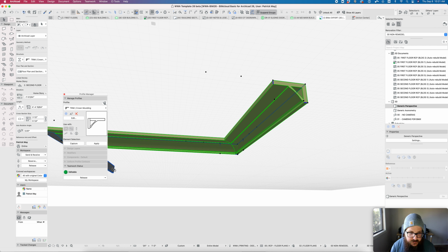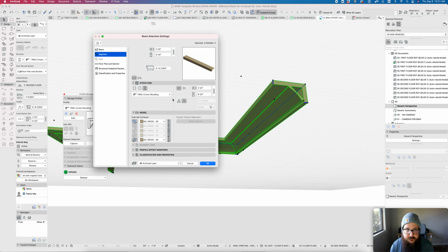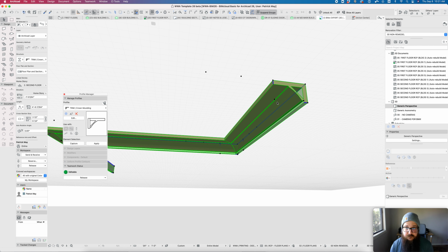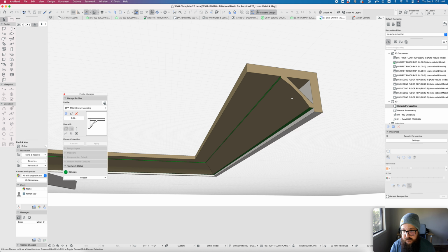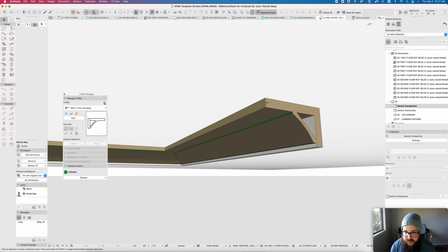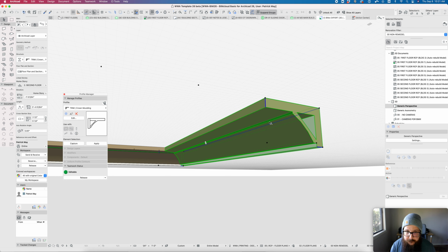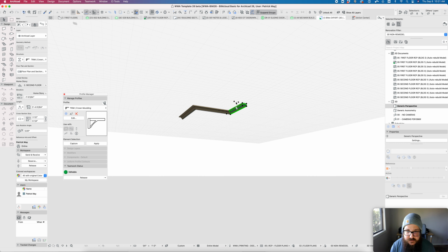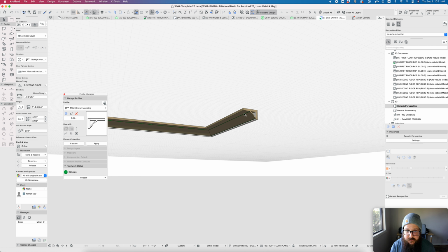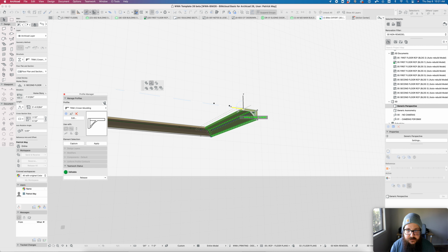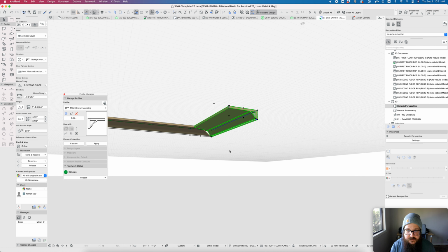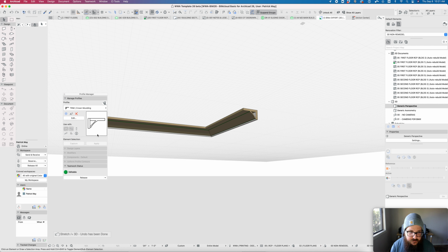Well, once we eliminate the surface overrides in the beam settings. Custom profiles are one area that I don't actually use model overrides for this exact reason, because I want to see these different surfaces being applied. And then here's these extra hotspots that I mentioned before. So now if I grab this piece and on the pet palette, I can stretch this to this point and snap exactly to one of these points. So that is creating custom profiles.